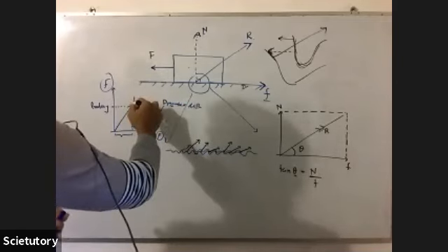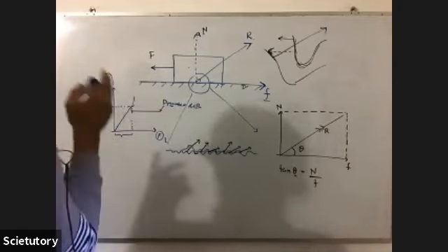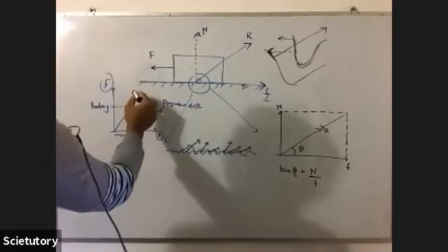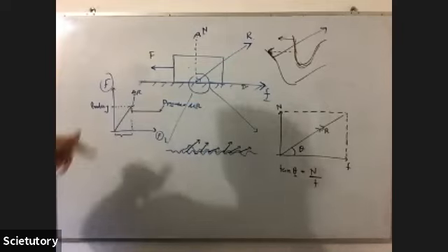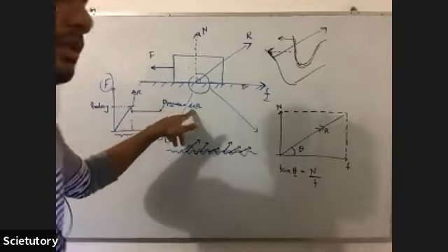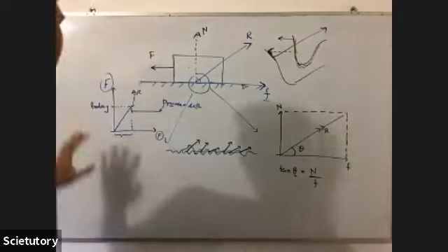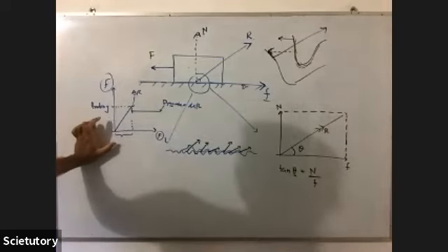And also you have one equation for this limiting friction, only at that point. That's also mu R, and here you should put the coefficient of static friction, and here you put the dynamic or kinetic one. Okay, so now this is the behavior.